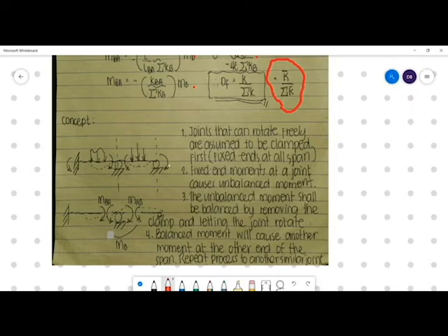So let's say you have here a continuous beam. Nakaka-rotate yung roller natin sa gitna, nakaka-rotate din yung roller sa dulo. So we clamp it, so we restrain all movement. So we assume na fixed tayo dito, fixed tayo sa span AB, fixed din sa span BC. So ano ang moment na nag-act dyan? That is your fixed end moment.